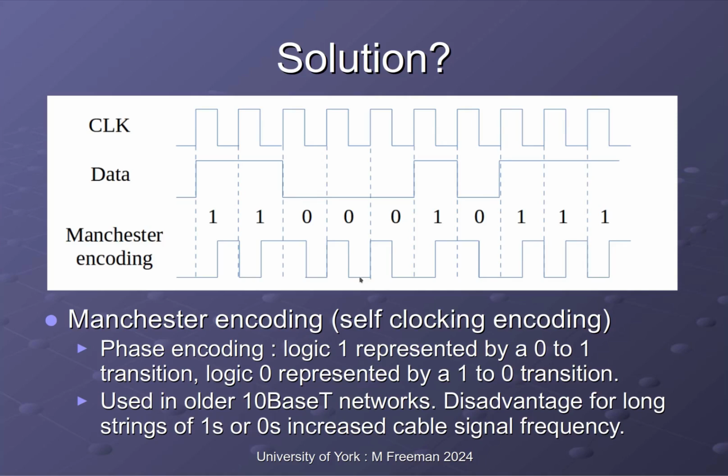So now our noise threshold isn't from 0 volts to 1 volt. It's somewhere in the middle. It'll have some DC offset, which makes it more difficult for the electronics to detect whether you're receiving a logical 0 or a logical 1.